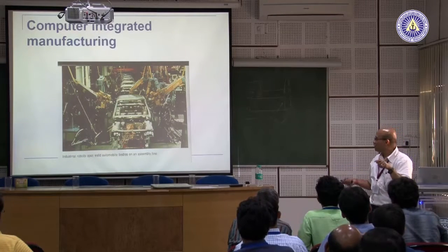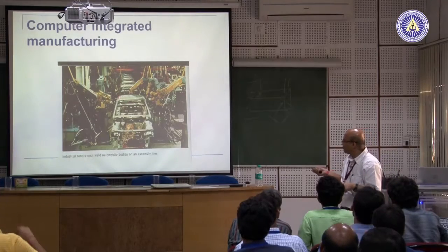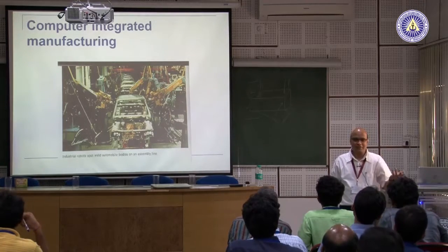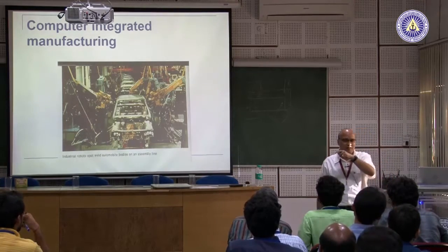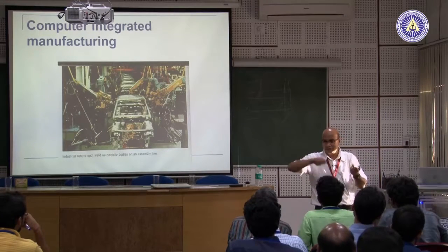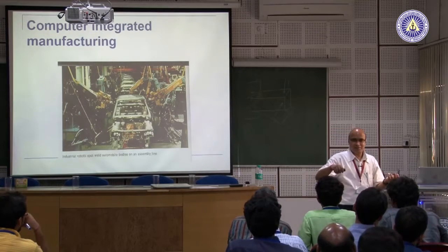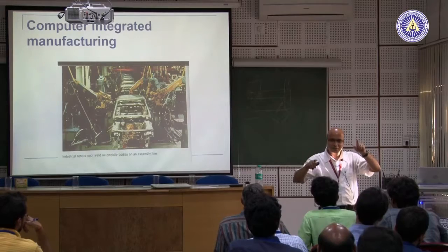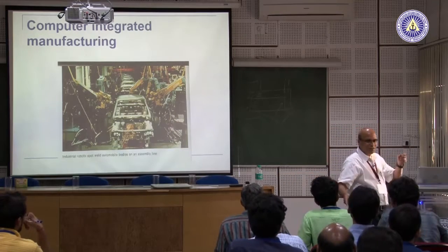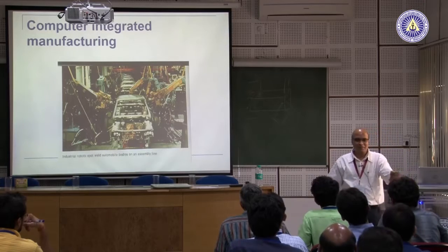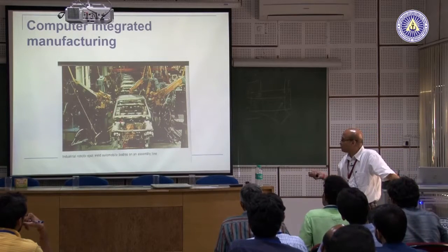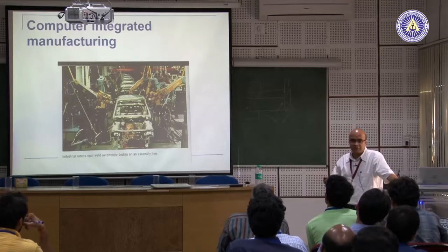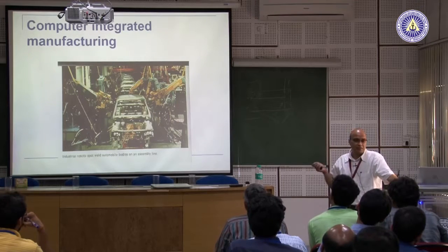Okay. Why? Because suppose we have a coordinate of a point there and we are wrong by say 0.0001 millimeter, that is next to nothing, right. 0.0001 millimeter is next to nothing. But if the robot is doing 3 shifts for 1 year, it will probably do a few million cycles. So, that million into 0.0001 is a big number, right. So, even a very small error cannot be tolerated under any condition. Okay. That is why the companies which do this are highly specialized, okay, and they do this CAD modeling, robot safety, the programming, and that is the one that is expensive.